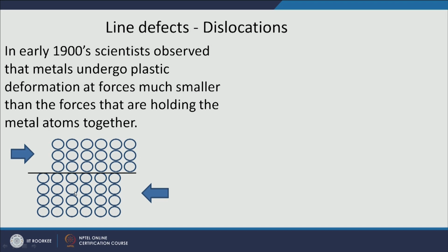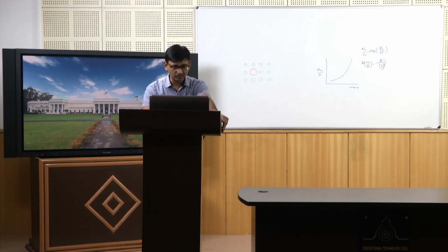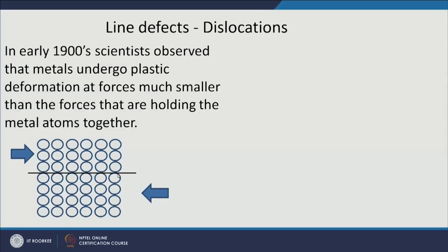So, you can see that in the previous arrangement there was some bond between all these atoms. Let me go back. So, you have all the bonds between these two atoms and this will be along the whole plane, okay. And when I am applying the shear, then all these bonds for all the atoms are going to break and they will form new bonds, okay.